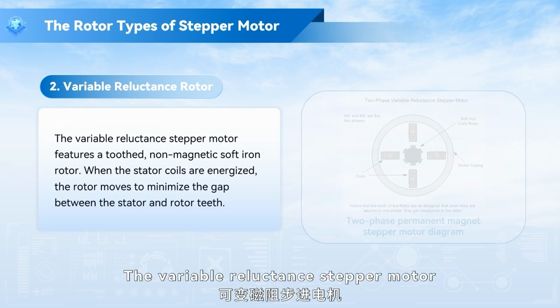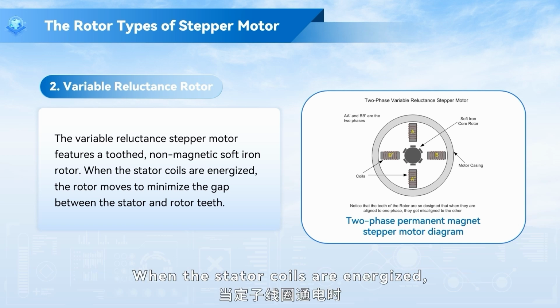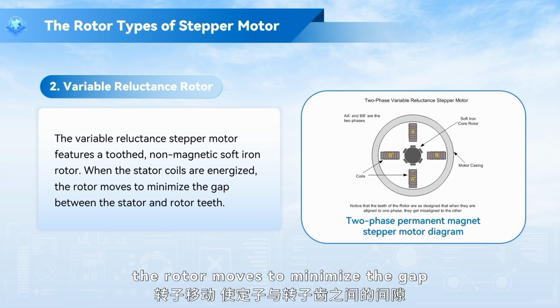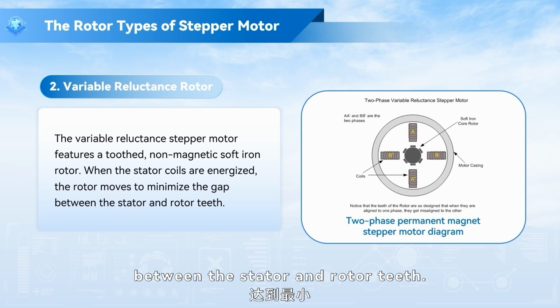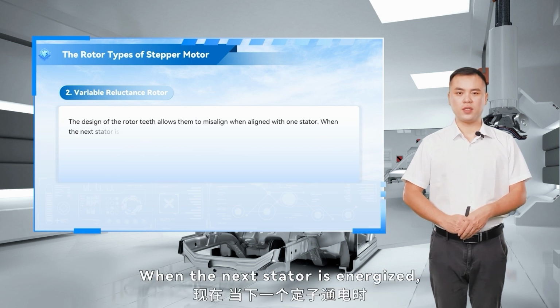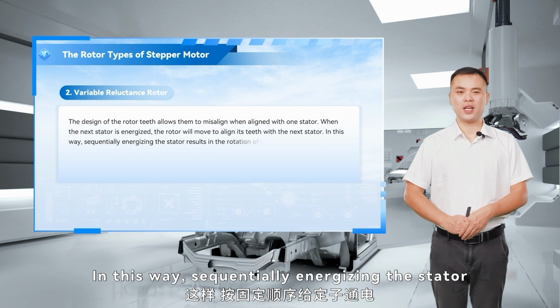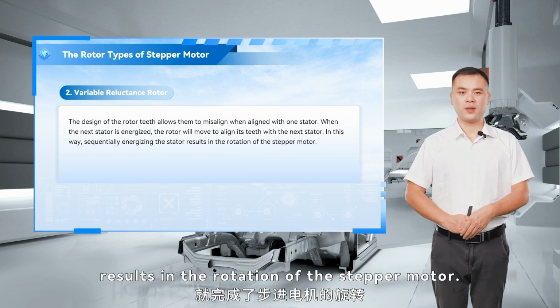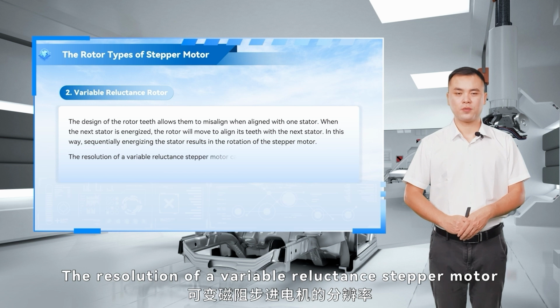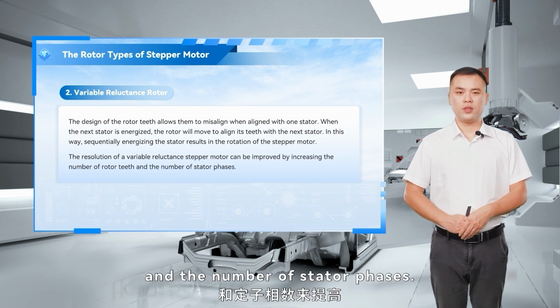The variable reluctance stepper motor features a toothed, non-magnetic soft iron rotor. When the stator coils are energized, the rotor moves to minimize the gap between the stator and rotor teeth. The design of the rotor teeth allows them to misalign when aligned with one stator. When the next stator is energized, the rotor will move to align its teeth with the next stator. In this way, sequentially energizing the stator results in the rotation of the stepper motor. The resolution of a variable reluctance stepper motor can be improved by increasing the number of rotor teeth and the number of stator phases.